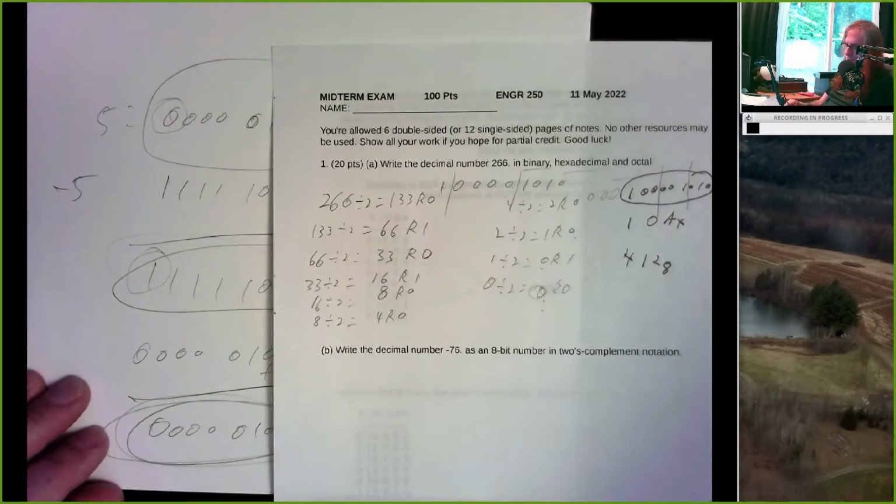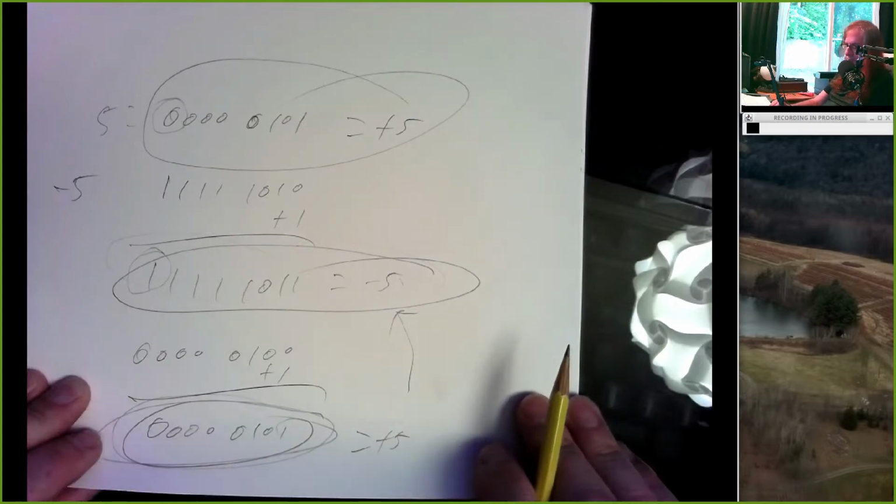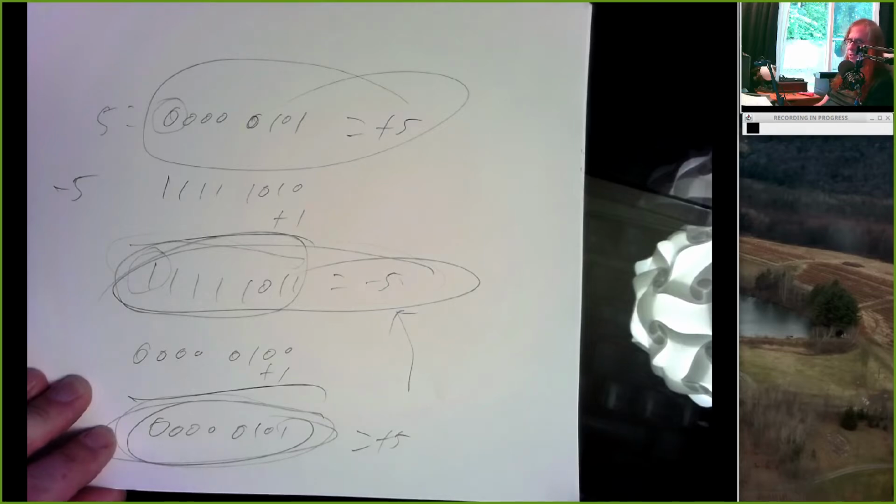What would happen if there is a 1 that is carried past the most significant bit? It flips back over into a positive number, but I don't think that can, well, maybe that can happen. But if you're doing 8-bit 2's complement, you just look at the low 8 bits. And if there's a carry out of here, don't worry about it.